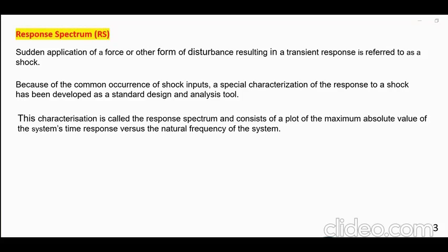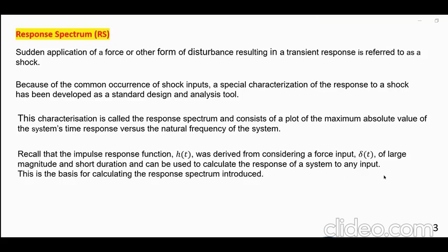Now, a particular methodology has been designed in order to do problems like that, and it involves getting the maximum deflection of the block, or the thing that you want to investigate, over the entire duration of the vibration. So the maximum entity can be displacement, or velocity, or acceleration, which in this presentation I'm assuming that we're interested in the maximum deflection, or displacement, of the block.